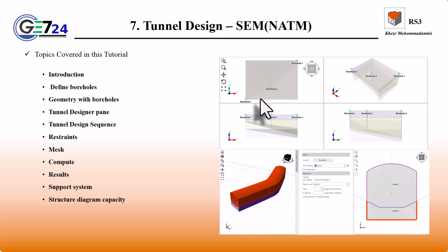It means staged excavation, tunnel phases, and also the mesh, compute, and results, and also design for the support system, how we can define the support system in RS3 for tunnels, initial support system and final support system, and results related to all of these supports like shotcrete, bolts, rock bolts, steel sets, rebar, and all of the support system, and also diagrams related to this support system,